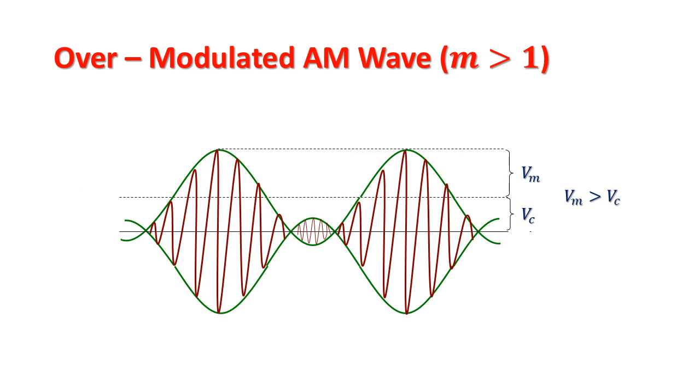The audio processor may also clip the audio if it becomes very close to the 100% modulation level. This will ensure that the carrier is not overmodulated.